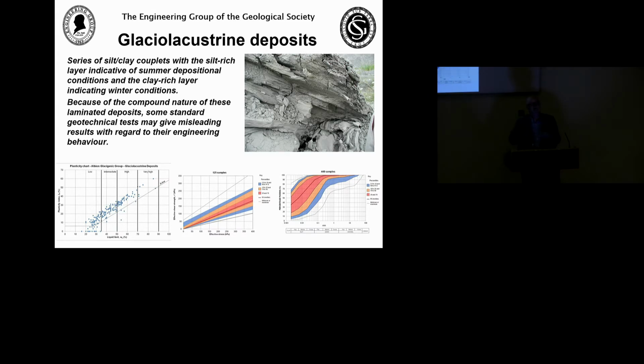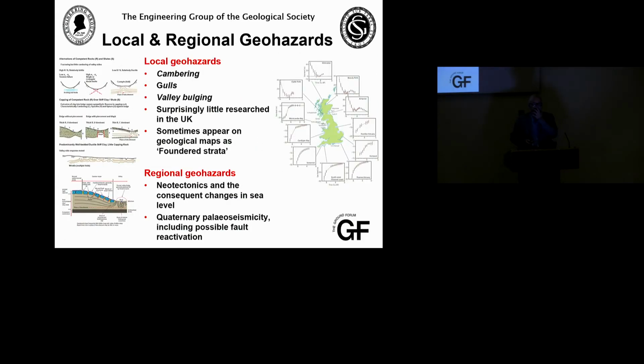So again, as a predictive tool, if you've got a former glacial lake, you can expect to find these glacial lake deposits. How do they vary geotechnically? What could you encounter? How may that help you when you test for them? What are you going to look for when you start to ram a shell and auger rig through them and destroy the fabric of the material? What might have been there before you buggered it up with your ground investigation? Simply because you didn't find it doesn't mean that it's not in that particular relic terrain. And that, again, was a very important aspect of the ground model development.